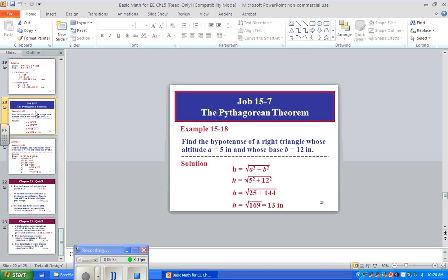This book discusses Pythagorean theorem. Pythagorean theorem is very simple. Hypotenuse squared is equal to adjacent squared plus opposite side squared, right? Very quick and easy, dirty, if you're only looking for a side. But in AC, we're never looking for just one side. We always need to know the angle because we're going to have one triangle that's a result of resistance, inductance, capacitance, things like that. And from that, we're going to get a power triangle. And the only thing they have in common is the angle.